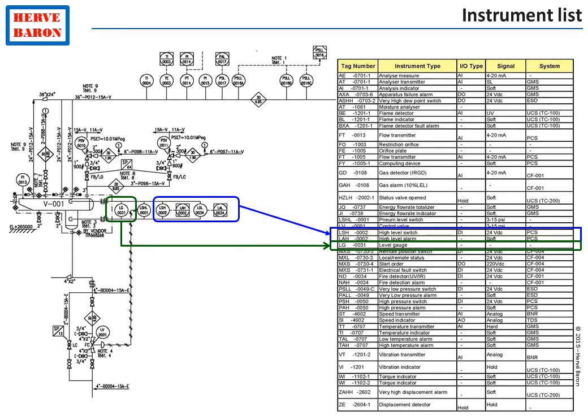The instrument engineer first task is to produce the list of all instruments specified by process on the P&IDs. This forms the instruments list or instruments database. This is a central document for the Instrumentation and Automation discipline. It will indeed list all the field instruments that are required to be specified, as well as the list of IOs, input and output, for the systems. So it will also give the capacity of these systems.